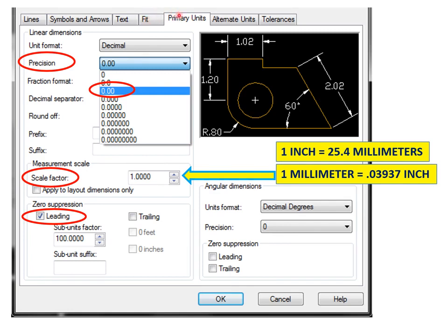But if your boss tells you, hey, I need you to change your dimensions from inches to millimeters, so instead of 2.02 inches, your boss wants you to change this to millimeters, about 51 millimeters. Then you have to go to scale factor. You go to scale factor, and you would change the 1 to 25.4.